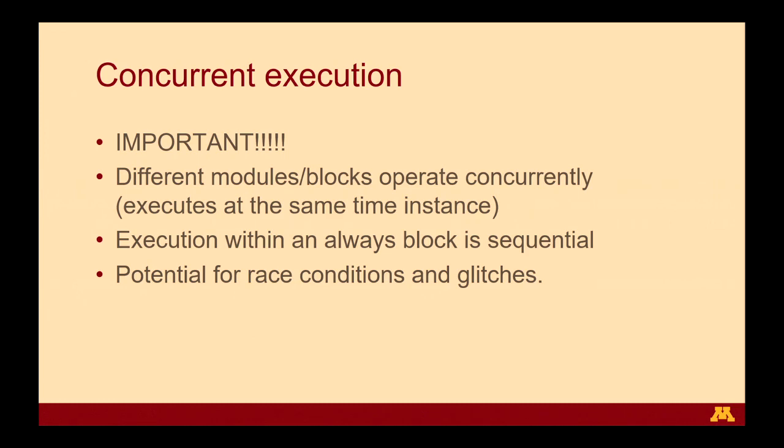In general, it's a very important thing to consider, because this is a very common source of mistakes, because most people do not account for the fact that these blocks execute in parallel. So they lead to a lot of conditions called race conditions, where the output is not known because two competing modules are trying to drive this output at the same time, right? So you'll not know the state of the output.